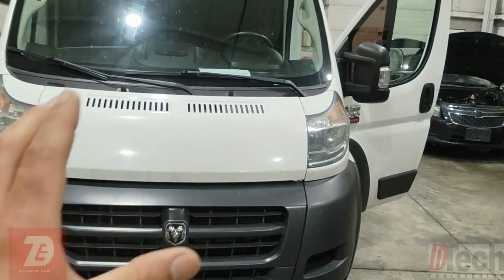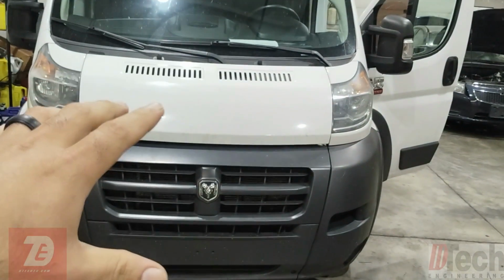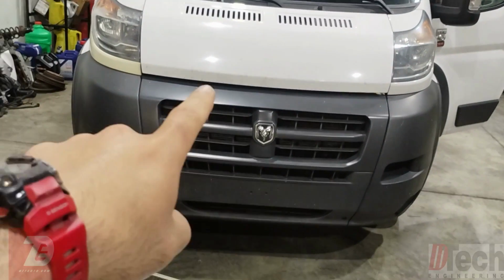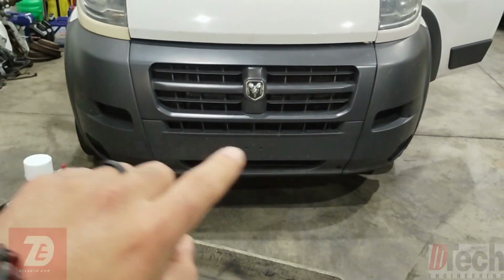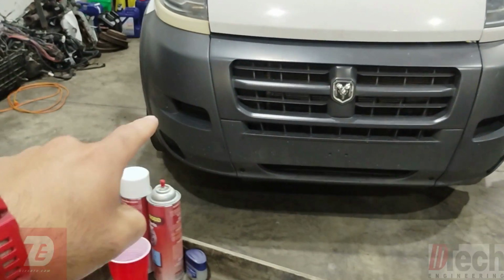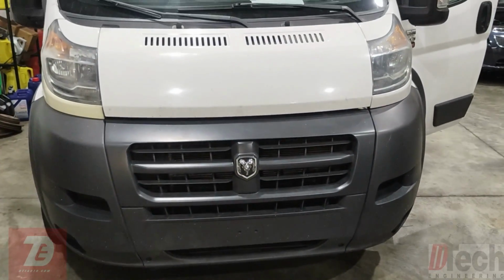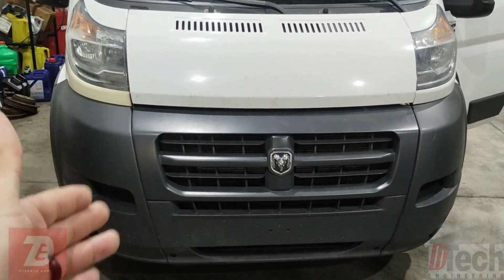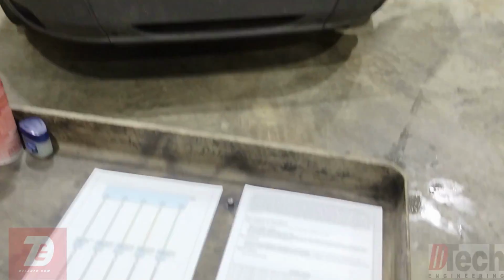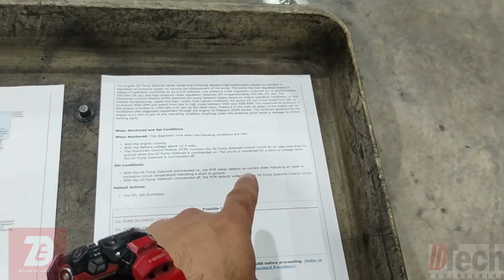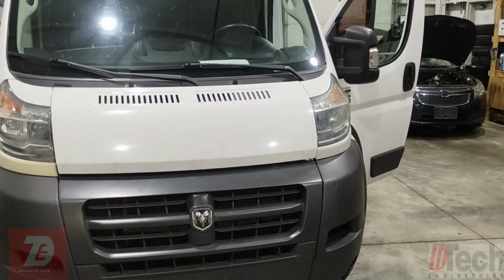and it's relating to that, which can also explain why any and all the parts that were thrown at it have not made any change, including the solenoid that the computer controls. So we know we have to deal with that system, but the solenoid is new and it is factory, so we can eliminate that physical solenoid being an issue. We're going to have to check from that connector up to the computer, hopefully find an issue, especially since it looks like there's ways to test that. And with that, hopefully we'll be able to make a determination.